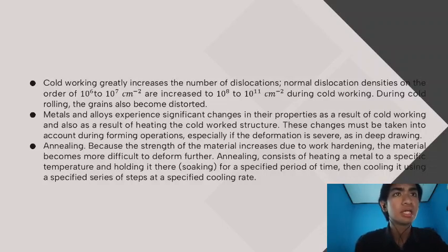During recrystallization, strength decreases and ductility increases, similar to that of the metal before cold working. Recrystallization can occur either during annealing after cold working or during the deformation process at a sufficiently high temperature to help drive the formation of new grains. The latter is referred to as hot working.